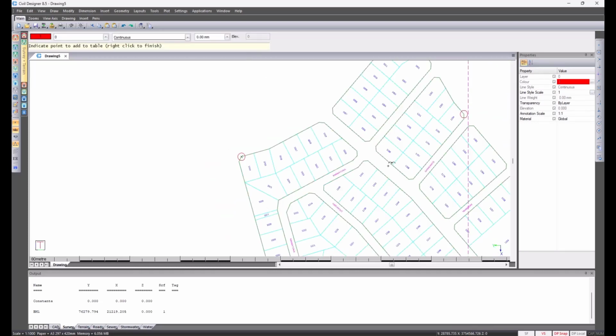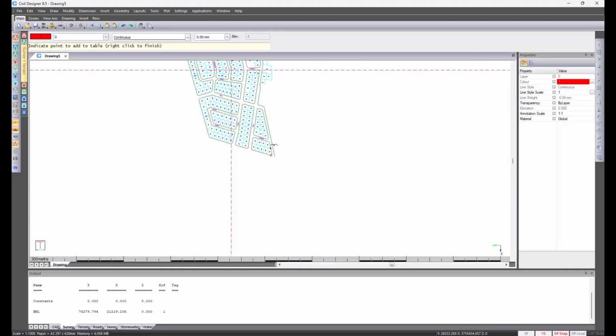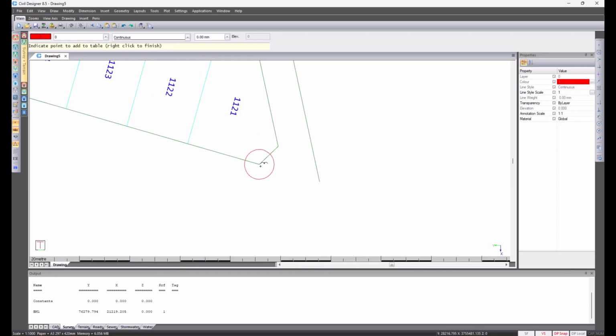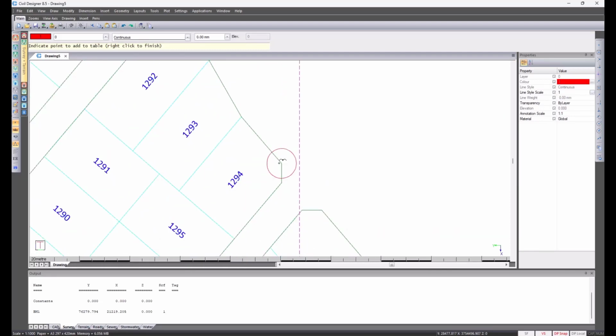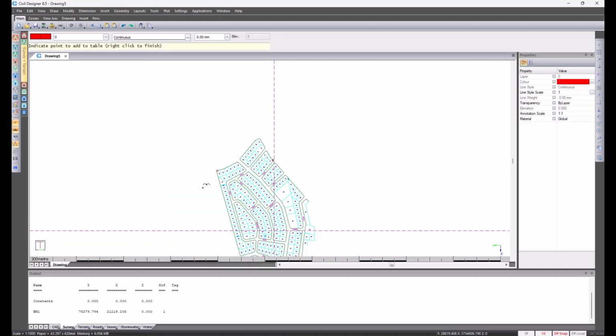Moving on to the next point, we'll head south. Place my cursor close by, press J, enter again. Specifying the new name, and then heading north again. We're going to use these 3 points for the transformation. Done with those 3 points, reading my prompt, I can right click and select finish.